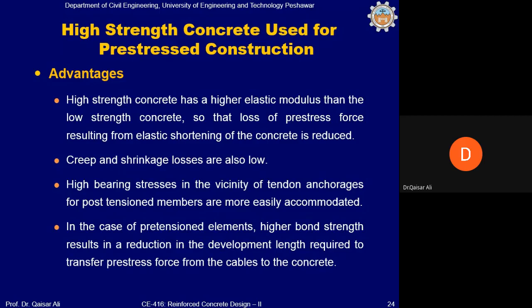This pre-stressing can be produced in another manner, which we will discuss in the coming slides in detail. But let me explain it a little bit right now. It is possible to keep a conduit inside the formwork, made of plastic or aluminum or some other material, a pipe inside the formwork, and then the cables or wires are passed through this conduit, and then concrete is poured without the steel wires or cables being stretched.